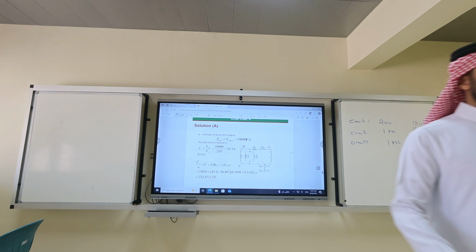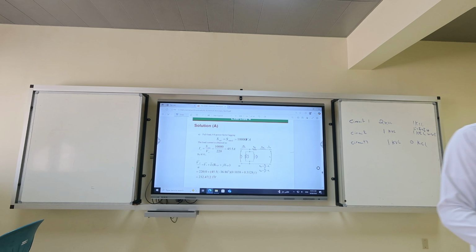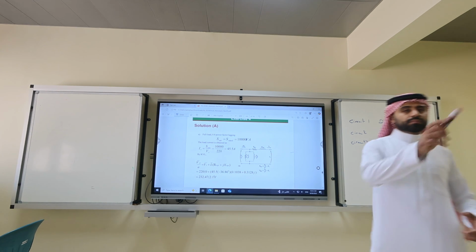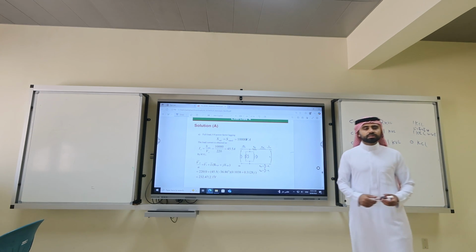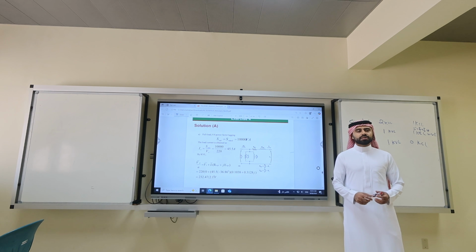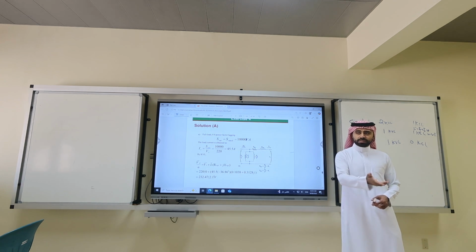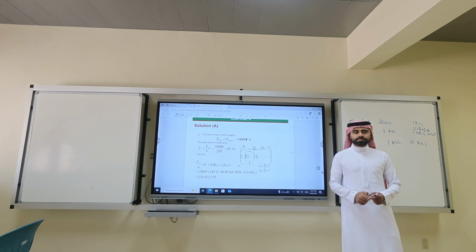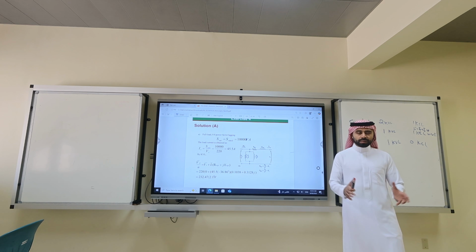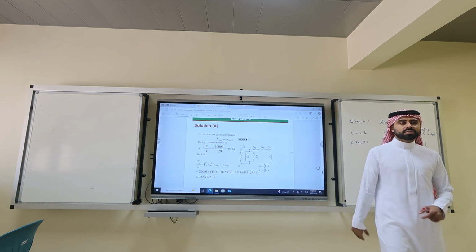Yeah, the nature of the load, distribution of them. Maybe it's a research problem for you. What are the real examples for capacitive loads? Capacitor banks are capacitive. Yes, but the bank you use to store energy, not to make a device. Not really. Capacitor load banks are used to inject VARs into the system.